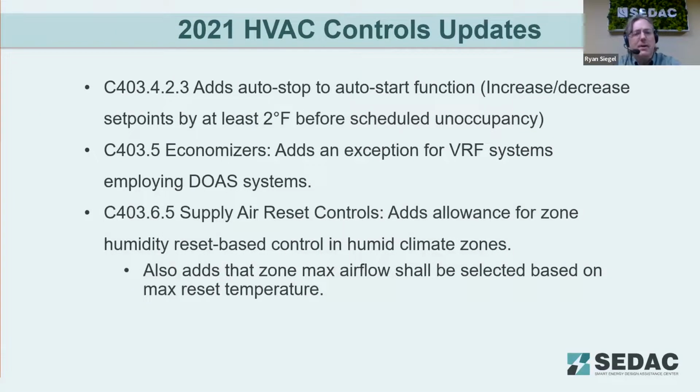So, also for HVAC controls, moving towards optimum start and optimum stop, that is, and trying to help add some coasting in. So understanding that a room, generally speaking, doesn't get uncomfortable immediately after the system turns off or sets back, helping to coast that building into the minimal occupancy time.